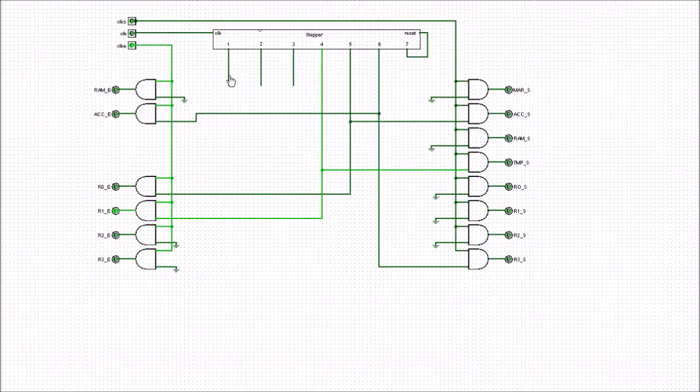So if we come down here, you can see that we've worked our way along, we've got to point 4, and at point 4 here you can see that the enable for R1 has now gone live, because this point here is live and the enable clock has gone live, so we've got a 1 there. But there's nothing going to happen at the set over here in the set section for this temp register until the clock set goes high. So let's make this clock set go high.